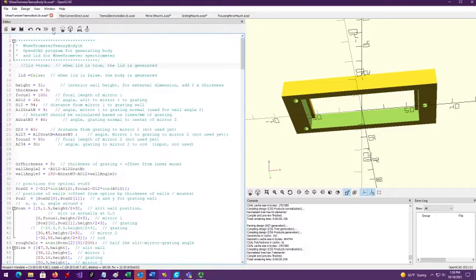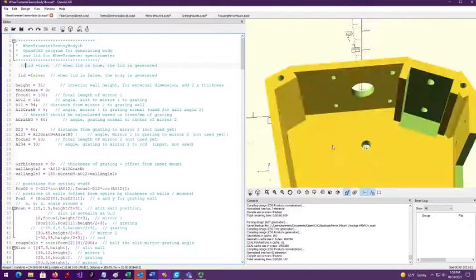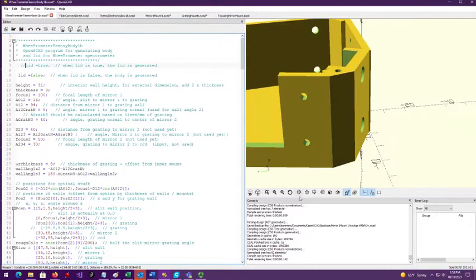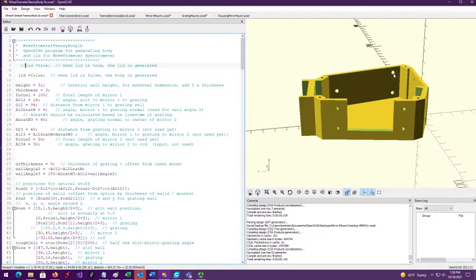Let's go back over to here and see where those attach. Okay, those 3 mounting holes, they attach through these holes here, right? And what we do is we put a piece of squishy foam behind the mirror, and you put the mirror mount on the other side of the mirror, and you screw, using sheet metal screws, you draw the mirror mount against the squishy foam.